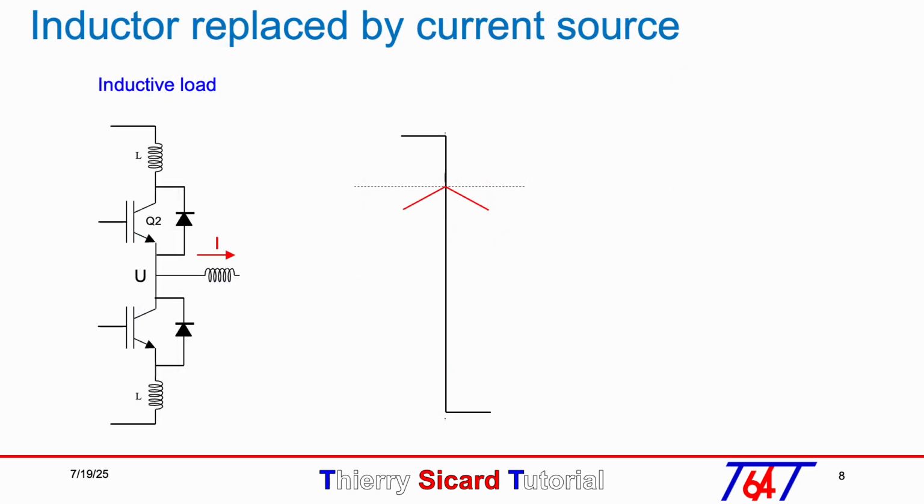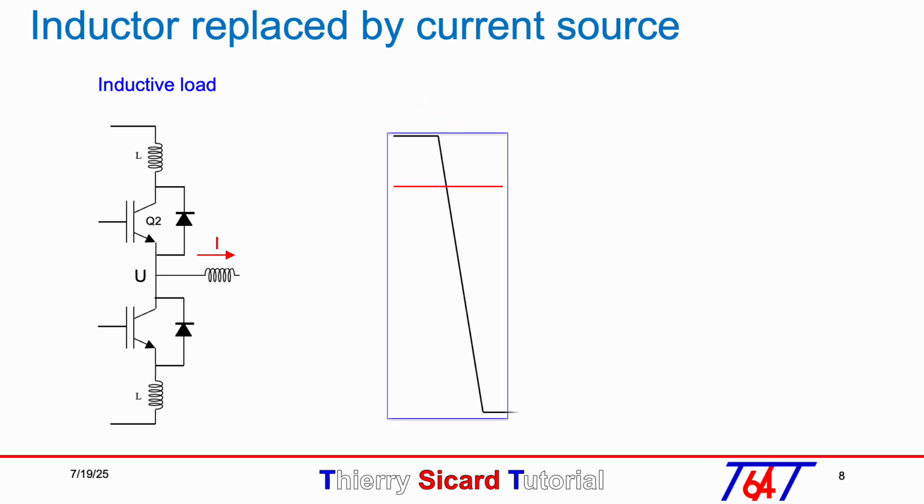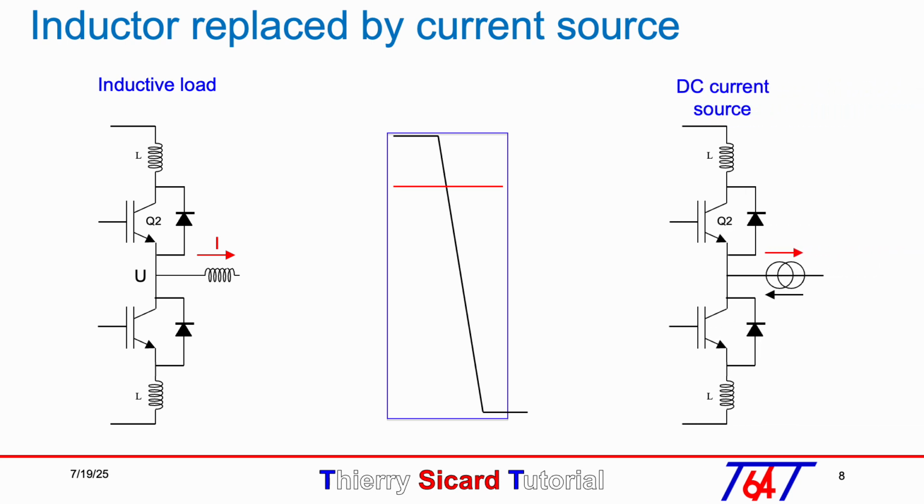The half-bridge powers the motor's inductance. During commutation, when the voltage drops with a very high negative dv/dt, the coil current simply switches from a positive to a negative slope. If we zoom in to observe the falling edge of the voltage, we see that during this edge, the current does not change. Therefore, for the simulation, we can replace the coil with a constant current source.